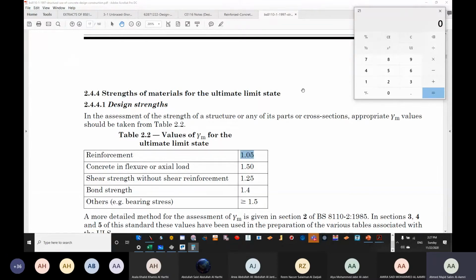You might be getting something 460, something lesser than that. So you need to give certain flexibility in terms of the value. So the code has told you if you're using 460, then there is a flexibility of 5%, which is 1.05. So now the value is 483. So the code says any bar which is more than 483 to 460 is acceptable.